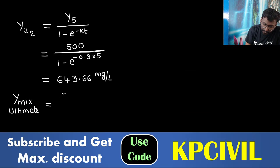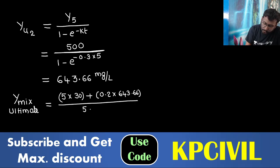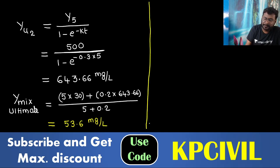So Q1 5 into Y1 30 plus Q2 0.2 into Y2, this ultimate only, 643.66, by Q1 plus Q2, 5 plus 0.2. What are you getting? The mixed ultimate BOD, weighted average, 53.6 milligram per liter.